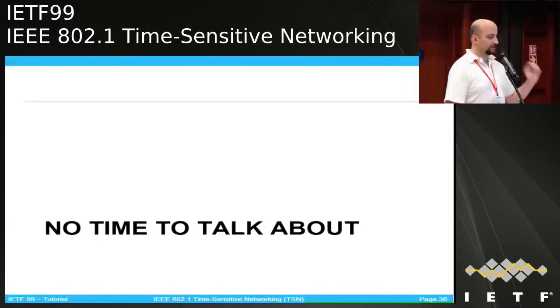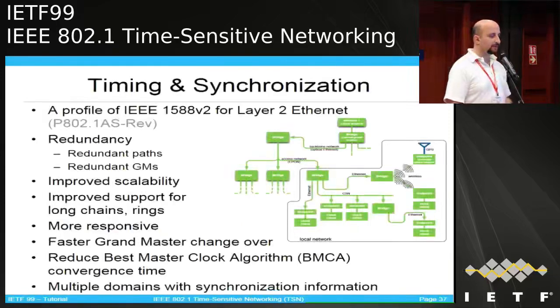So this is what we planned to talk about, and we have some stuff going on and available. We have no time to talk about it, just to flash time synchronization. I mentioned in the beginning, it is very important. For example, for the time-gated queues, you have to know the time to program your schedule, or for the cyclic queuing. And we have a standard for that, 802.1AS timing and synchronization, which is a profile of the IEEE 1588 precision time protocol for layer 2 Ethernet bridges.